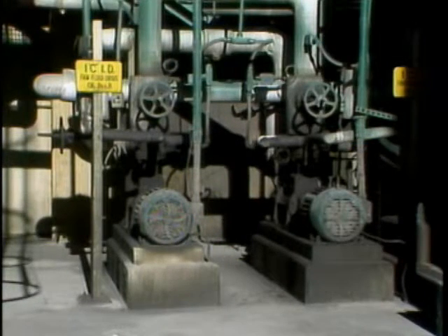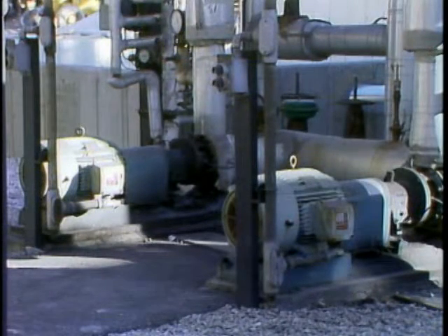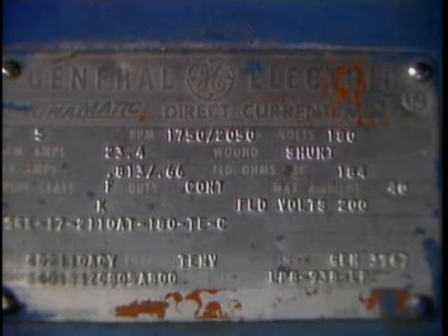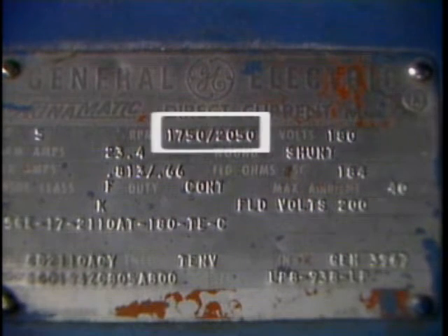Motors are also used in some process systems as final control elements. Motors provide the driving force to move, operate, or position components. For example, this variable speed motor is used to run a conveyor. Changing the electrical power supplied to the motor changes its speed, which slows down or speeds up the conveyor. While some motors are variable speed motors, many of the motors in a plant operate at only one speed. The output speed from a single speed motor can be controlled by connecting it to the process through a variable speed coupling. In this case, the coupling acts as the final control element.